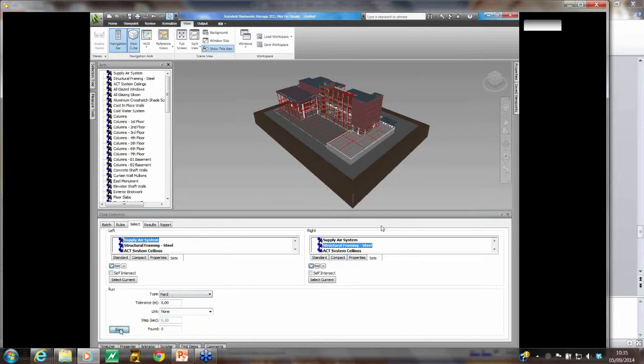But we also have the ability to link to the 4D Timeliner, the construction sequencing that I've just demonstrated to you. We have the ability to link that to Clash Detective. So that once again, as we're working our way through a level 2 BIM model, we're construction sequencing and we're linking events to project management software.